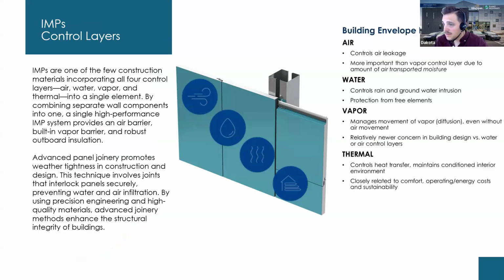They perform well on facades because they don't absorb moisture, but the difference is that glass and steel on their own lack the thermal performance needed to act in a high efficiency manner, especially along the whole building envelope. They're good for some of the translucent surfaces, but we can do better on the opaque.